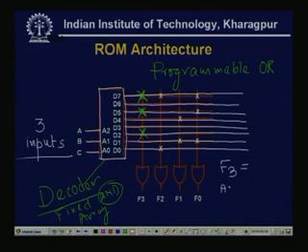So, this is A, B, C plus, say, D5 means 101, that means A, B bar, C, plus D2 means 0 1 0, so A bar, B, C bar. So, my F3, one of the outputs, is ABC plus A B bar C plus A bar B C bar.